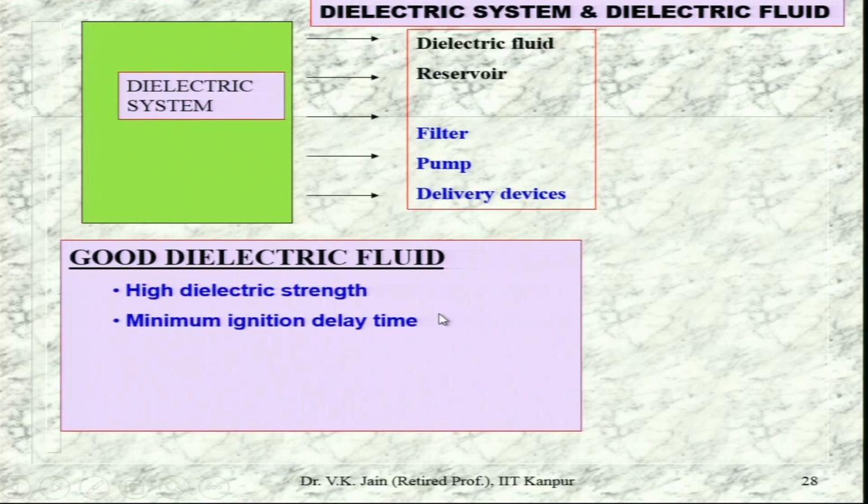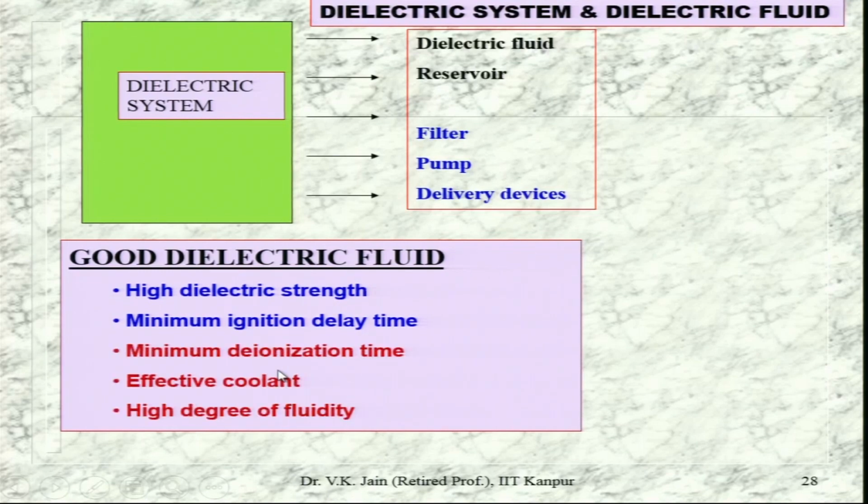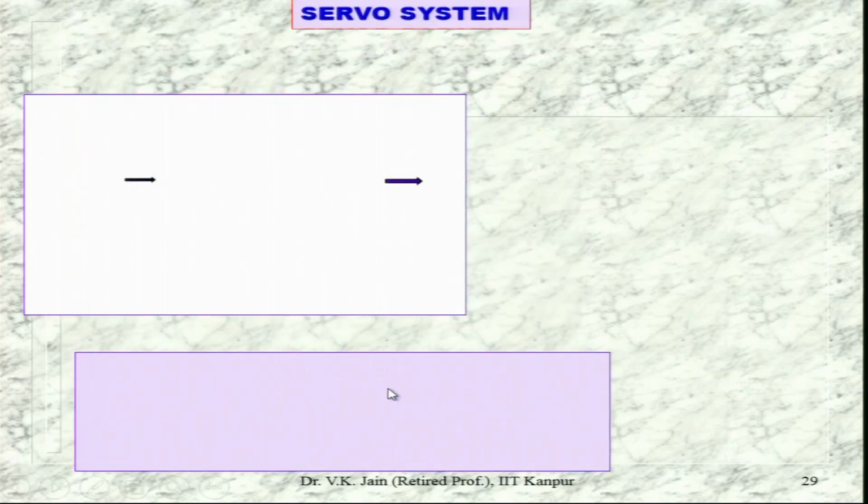A good dielectric fluid should have high dielectric strength, so that you get a higher material removal rate, minimum ignition delay time, minimum deionization time, it should work as an effective coolant, and a high degree of fluidity. These are the desirable characteristics of the dielectric.